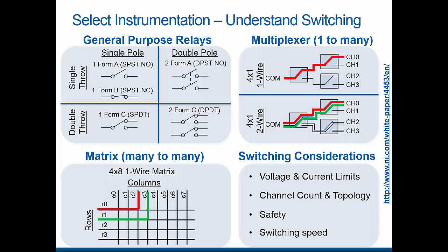Say our test procedure required a short from column 6 to column 7. This would be very easy to do with a matrix as shown here. However, this flexibility comes with a price, because it's possible to accidentally short two signals together. In our example, what if we forgot to disconnect C2 before measuring C4? You can see that this causes us to accidentally short from C2 to C4, potentially damaging the UUT or test equipment.